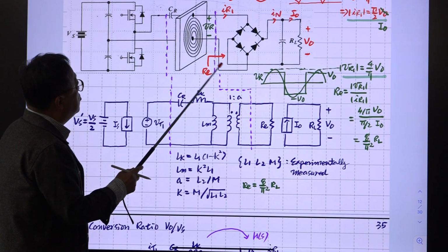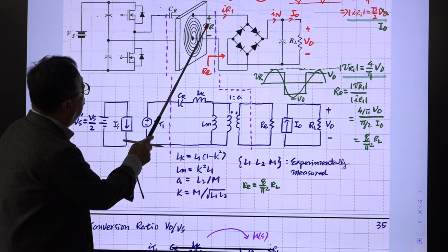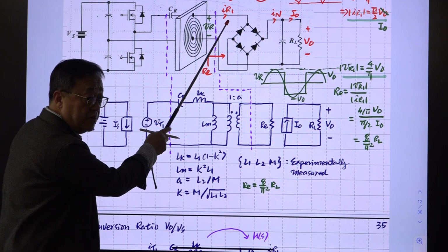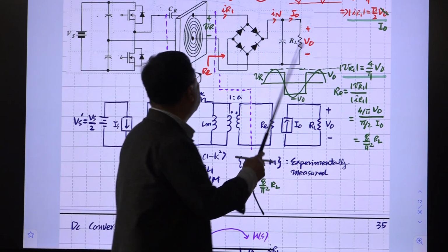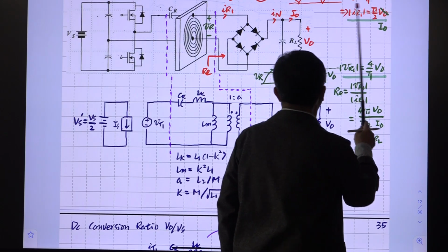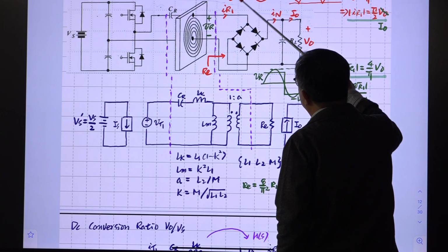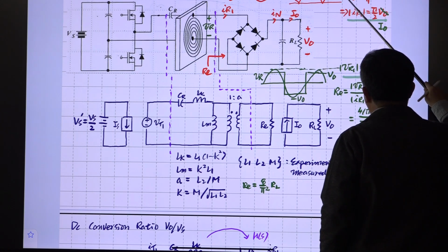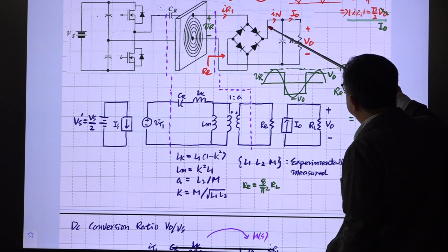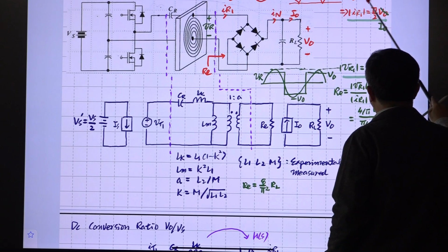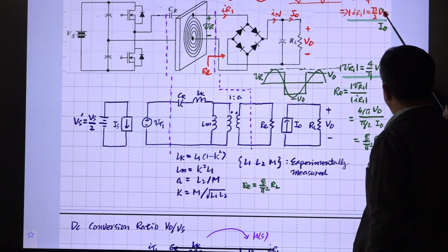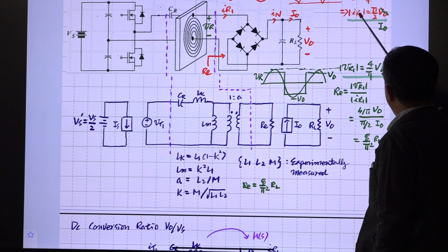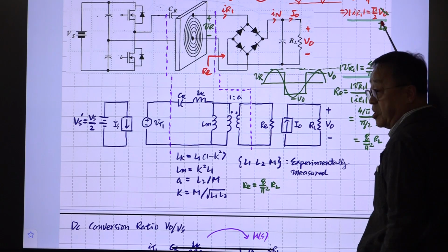We are trying to find the ratio of magnitude of this VR1 and IR1. Okay. So the relationship between IR1 and the IO is this one. Because the sinusoidal waveform is rectified here, and the average value of this becomes IO. AC component is entirely passing through this capacitor. So we have this relationship. It's not a VO, it's IO. Okay. Then we have this relationship. IR1 magnitude is, we have expression here.